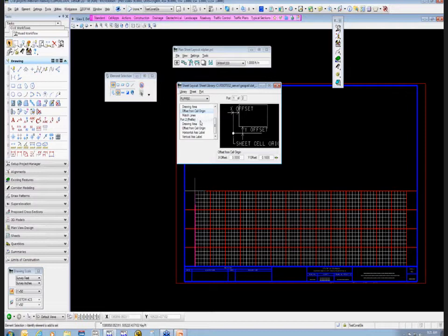If I look at the profile port, it's not quite as tall, so it's giving it a different height. I've got my drawing area, and it's also saying I'm going to use this X offset, it's going to stay at 0, and then it's going down the 4 feet so that it starts down here at the bottom. So this whole area gets clipped out as a clip border boundary.